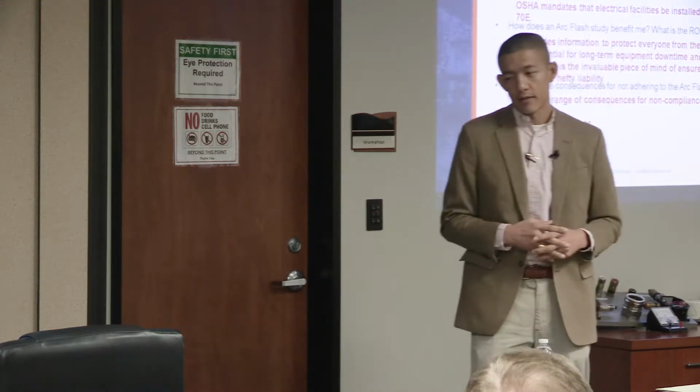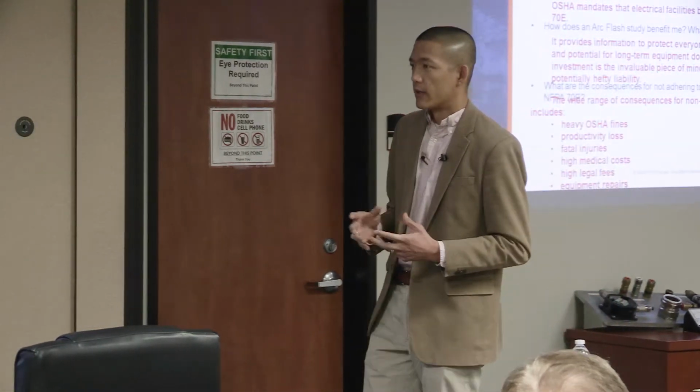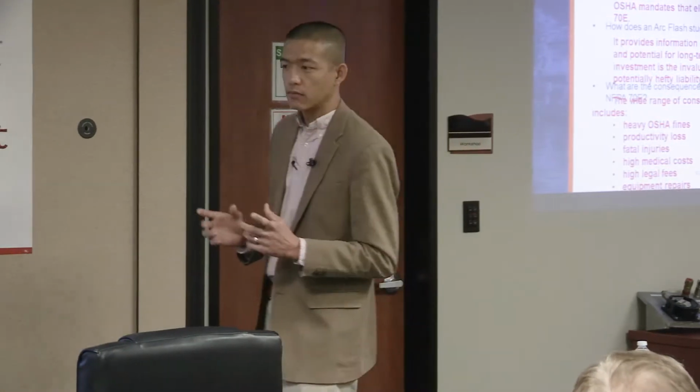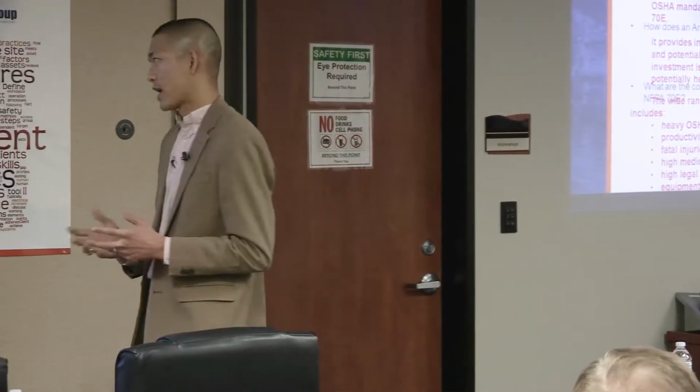NFPA 70, in the older versions, they actually only had a little snippet in there about requiring arc flash stickers, and those are just standards. There's nobody that's going to come in from those agencies and fine you, but OSHA does absorb those standards into their toolkit, and they're the ones that can fine you based on those standards because they have adopted those.